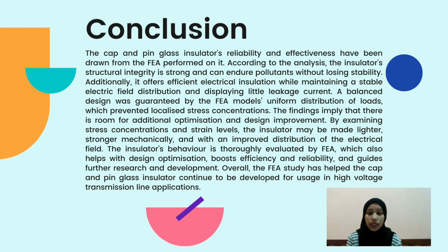For the conclusion, important conclusions about the cap and pin glass insulators, reliability and effectiveness have been drawn from the FEA performed on it. According to the analysis, the insulator structural integrity is strong and can endure pollutants without losing stability. Additionally, it offers efficient electrical insulation while maintaining a stable electric field distribution and displaying little leakage current. A balanced design was guaranteed by the FEA models, with uniform distribution of loads which prevented localized stress concentrations.